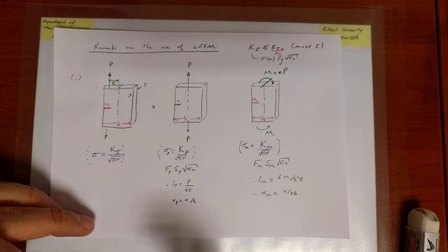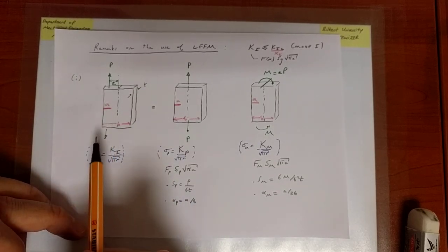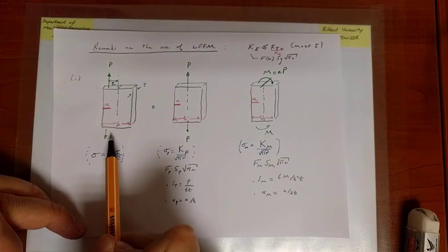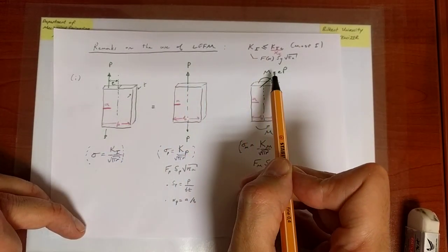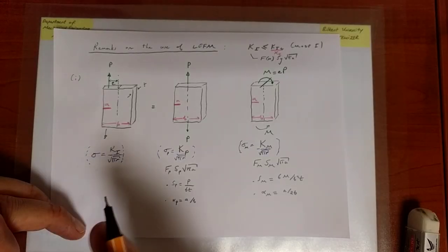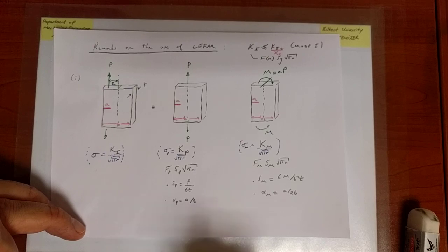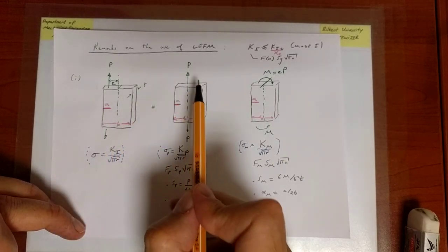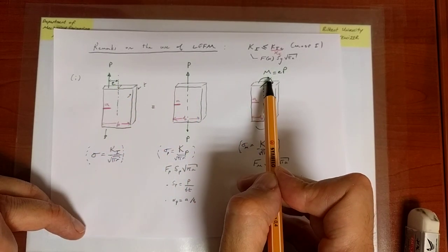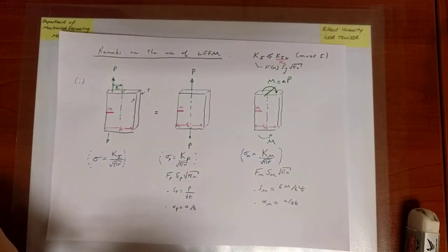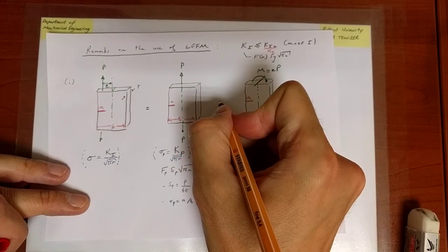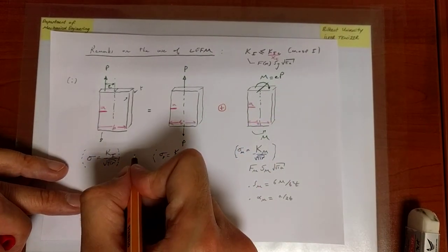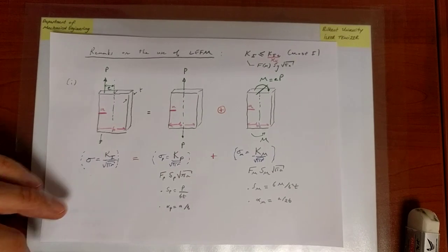And now, if I were to ask you, I am interested in the stress field for that scenario, and I know the stress field for this and that scenario. In this scenario, the loading is equivalent to the sum of that plus that. So what is the stress field? If I ask you the question in this fashion, you would probably come up with the idea of superposition, because we're doing linear elasticity. And in linear elasticity, we know that if the geometry is the same, and you have a loading that is a combination of two loadings, the resulting stress field is a combination, and in fact, a sum of the two stress fields. So conceptually, this problem is a conceptual sum of these two problems, and that problem, therefore, is going to be, as a result, a sum of these two problems.